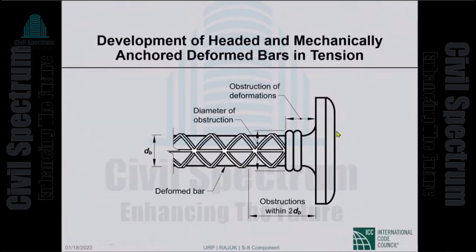So this is a headed bar. This is the bearing face of the head. Okay, this bears on the concrete. So the idea of headed bars is that part of the stress is transferred from steel to concrete through bearing of the head on the concrete, and the rest of the stress is transferred by development along the bar.